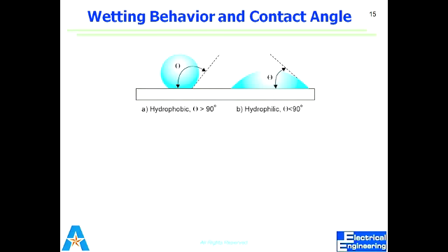It will always show a resistance to the water passing through, because it's very small. It's already having some resistance to letting anything pass through because of the very small hole. So I need to make sure that the polymer that I am depositing on the pore is hydrophilic. In that case, I can use that polymer in my experiment, otherwise I cannot. Otherwise you cannot run the experiment, because if that polymer is hydrophobic, it is named as wetting of the pore.